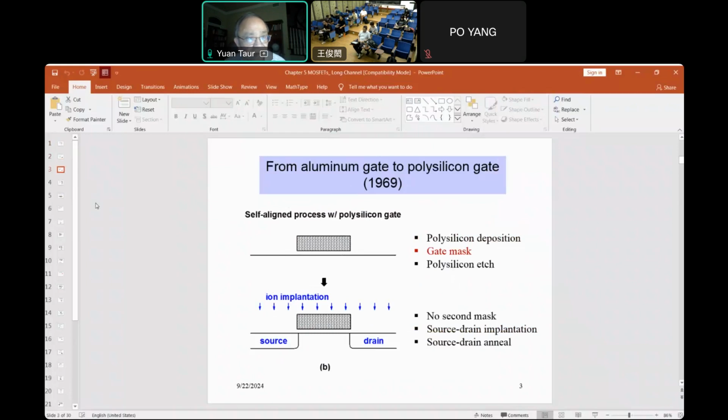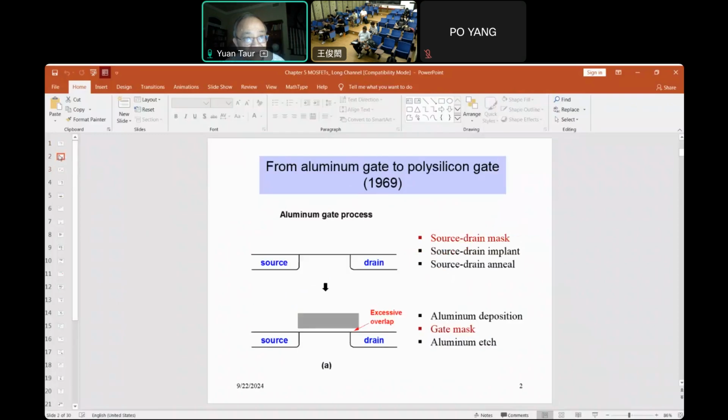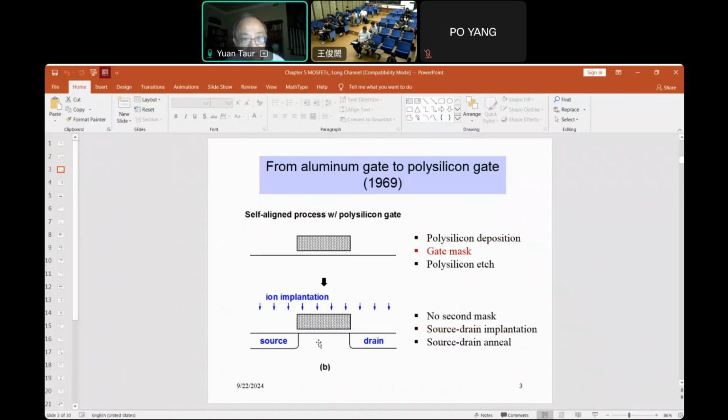So even though the industry went from metal to polysilicon and back to metal, that metal is not the same as this metal. It's done after the polysilicon, and we replace the polysilicon with the new metal. And you have to have two metals. For polysilicon, you can dope the NMOS side N plus poly and the P region P plus.